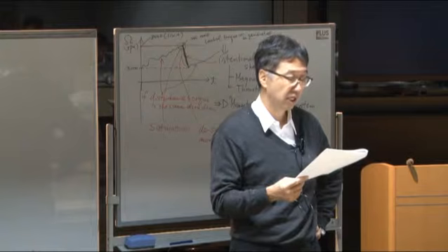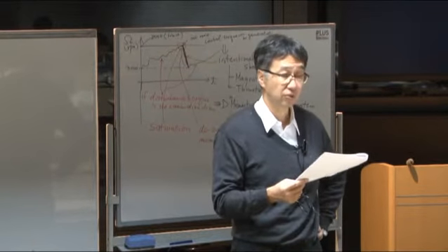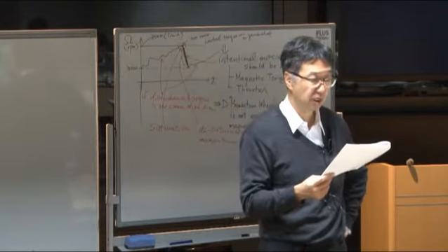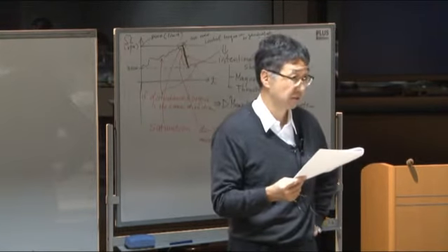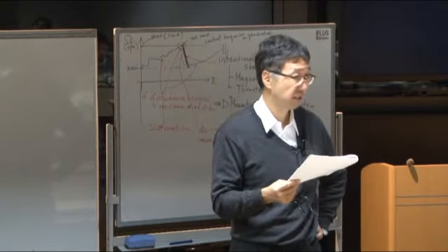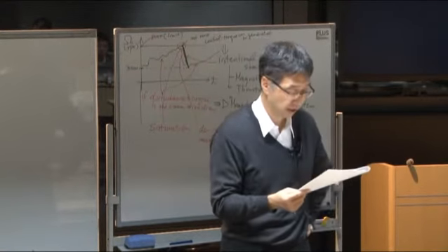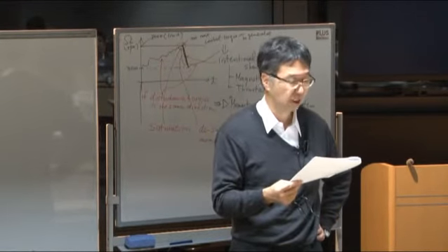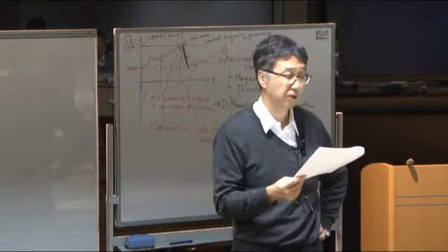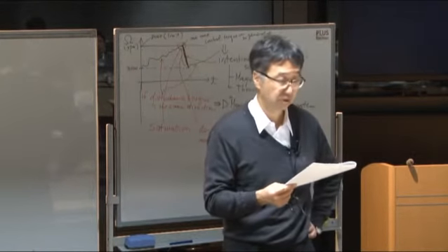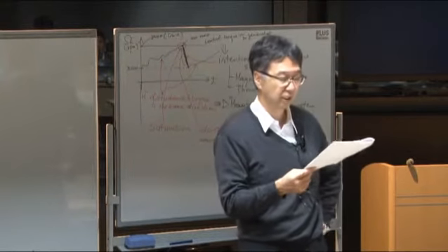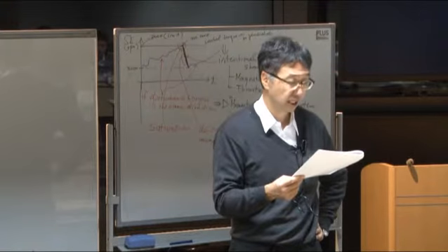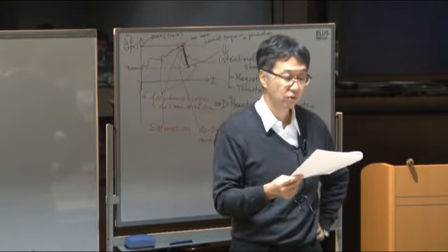And why this kind of skew direction of the wheel? This is because the skew wheel can generate torque around the three axes. Not one axis, but it can provide torque for the three axes. So this kind of four wheel configuration is very typical for reaction wheels. Our HODOYOSHI satellite and the Uniform satellite have a four wheel configuration: the XYZ, and the last one is a skew.